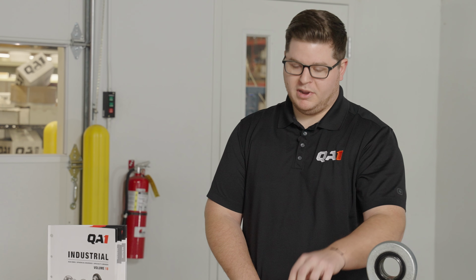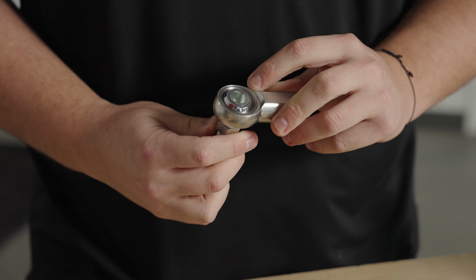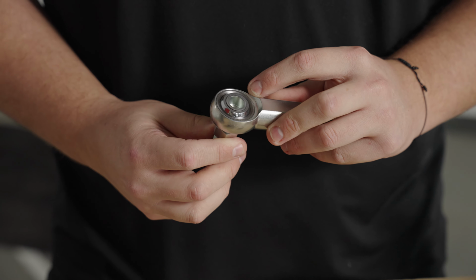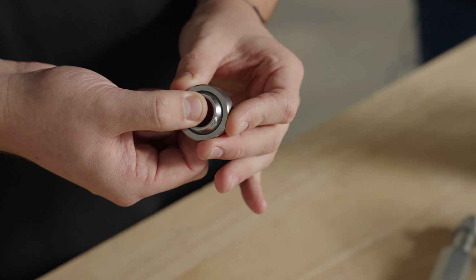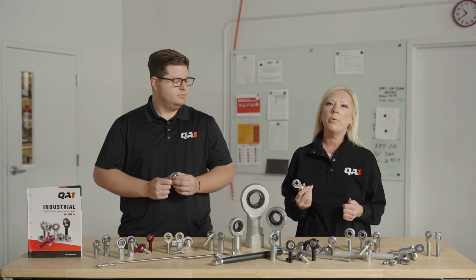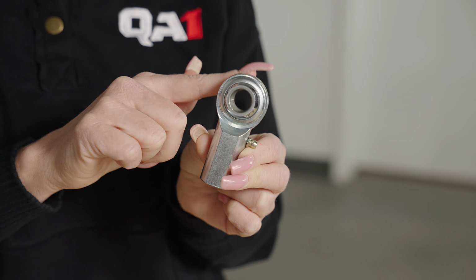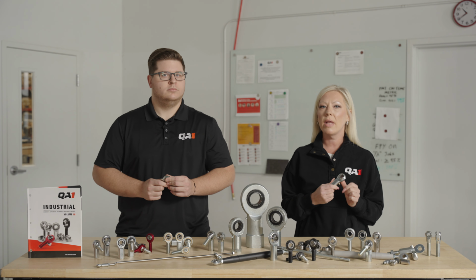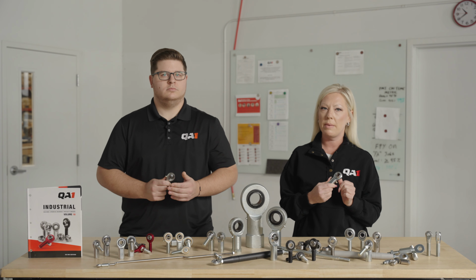Let's get started by reviewing what rod ends and spherical bearings are and how they're similar. Both use the same basic mechanisms, a spherical ball that allows oscillation and misalignment under load. And both rod ends and spherical bearings include a through hole or bore for mounting a bolt or pin. Also, both components rely on a ball that manages angular movement and carries radial loads. So internally, they're more alike than different, and the bearing mechanism itself functions exactly the same way.